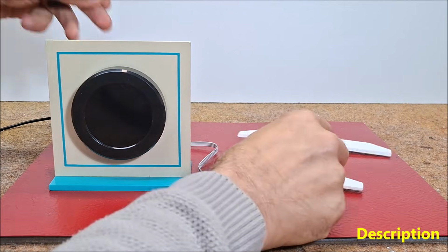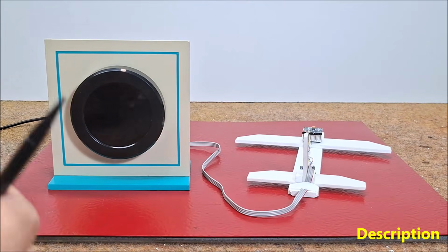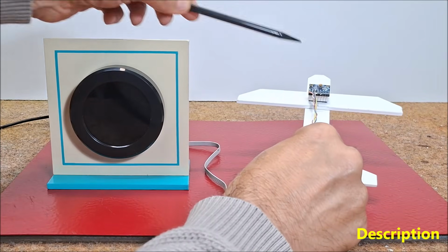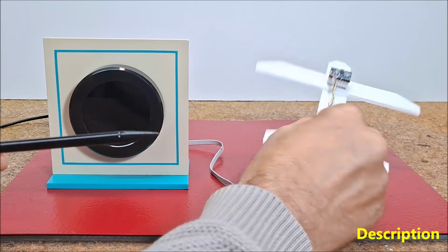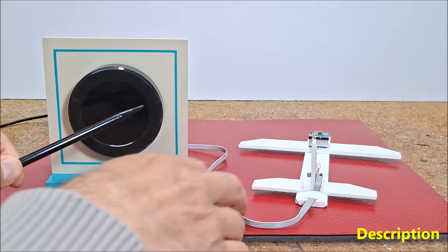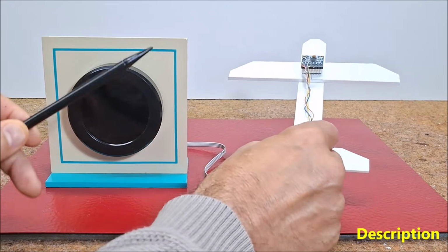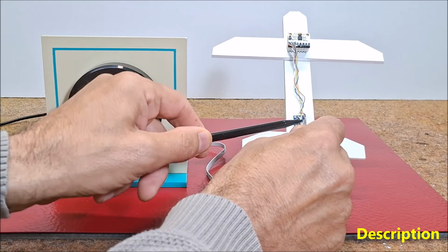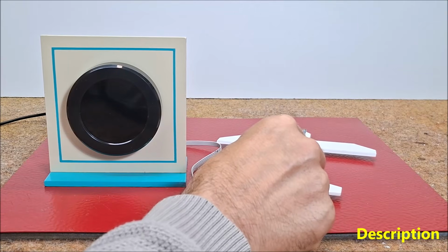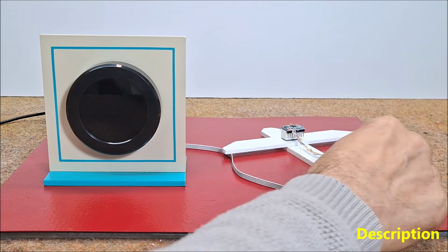The MPU6050 6-axis accelerometer and gyroscope module provides information about the pitch and roll orientation of the model. These measurements are processed and converted into graphical movements on the display. In addition, support for a QMC5883L magnetic compass sensor was implemented to provide heading information for the compass instrument.